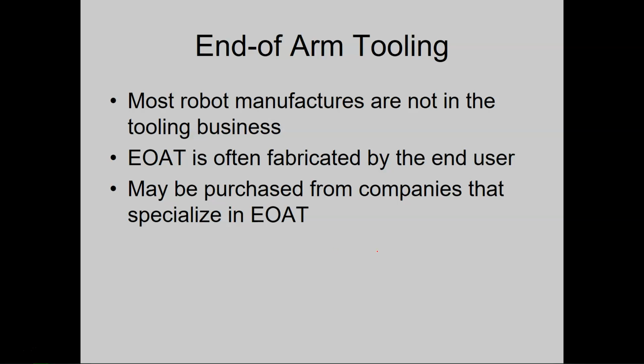So what I mean is that if the robot is in a certain position that's like right out here doing whatever it's doing, this is its total path, there might be machinery on either side of this path, and if you tell it to go back to its home position, which might be like right here, you're going to wipe something out, which will tear up your tool, it'll tear up the work cell. It's a bad idea. So what you need to do is go back along the path you came in to get back to where you need to be.